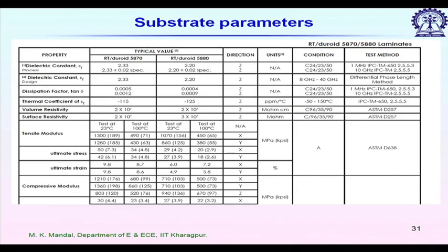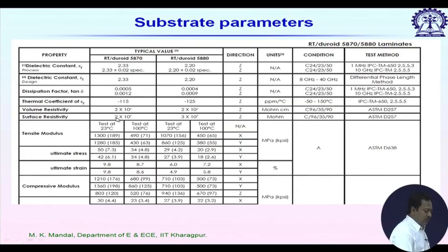With this, there are additional parameters, like what is the Young modulus of your substrate, what is the vapor absorption coefficient of your substrate, because if the dielectric absorbs vapor, water is very lossy, and the dielectric substrate will become very lossy. So, there are many other factors we have to keep in mind.